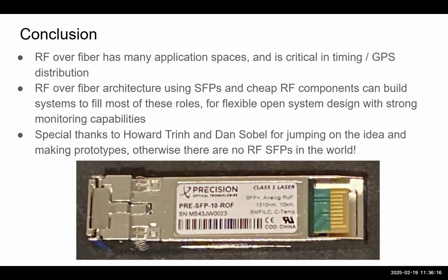Distance: this particular part was an LR, 10 kilometer. There may be applications where a shorter distance is required, or longer. A standard SFP+ is capable of over 100 kilometers, subject to testing the analog transmission, with different transceivers. So all of that is customizable within the 10 gig SFP standards, and we're able to do that on this part.